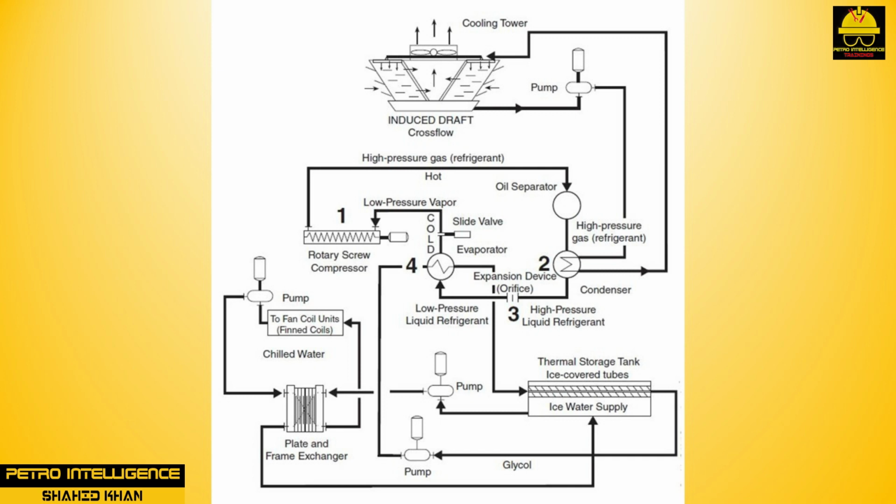When the pressure on refrigerants is released, however, these liquids boil violently, and their temperatures will drop considerably. Propylene is a good example of such a liquid. Its boiling point at atmospheric pressure is -54 degrees Fahrenheit. Propylene is normally a gas, but using a compressor can liquefy it. In compressing any gas, work is done, and heat is generated in the gas. In compressing propylene, we add heat to the gas and raise its temperature. Raising the temperature allows us to cool the compressed gas with water, and in this manner the propylene is liquefied.